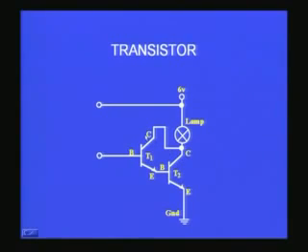Now what I want to show you is the current gain of this transistor is so large that if I now connect between these two terminals at the base for providing a forward bias, I have to connect some resistor or something here. But this resistor, previously I used some lamp and LDR and all that. Instead, if I now connect my hand, two hands, one hand here and one hand here, you would find I will be including my body resistance, right? Everybody has got a body resistance. It depends on the skin temperature and things like the dampness of the skin and all that. So it will normally be very, very high, of the order of several megohms.